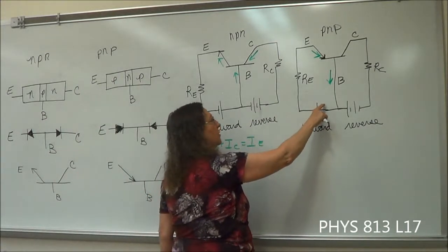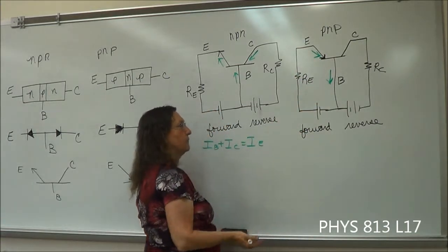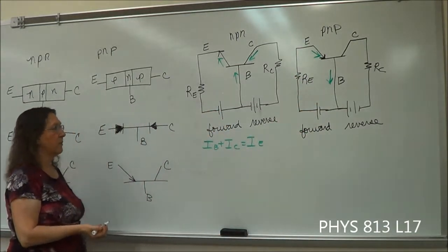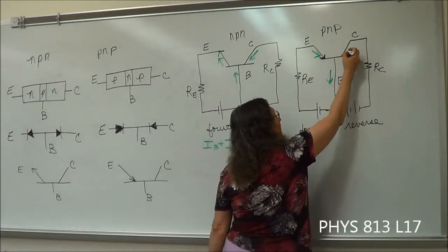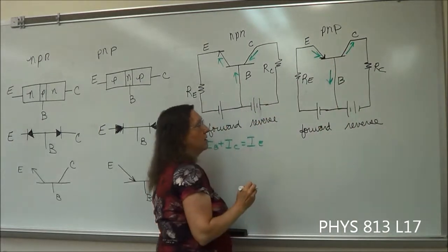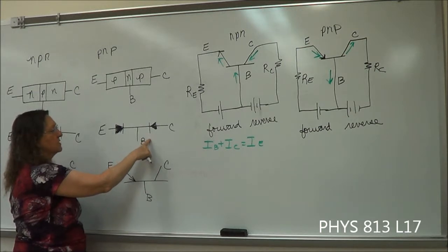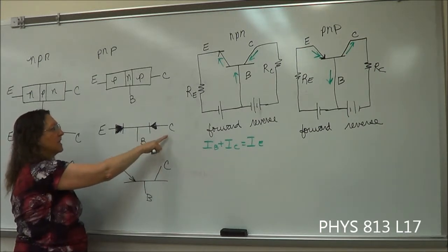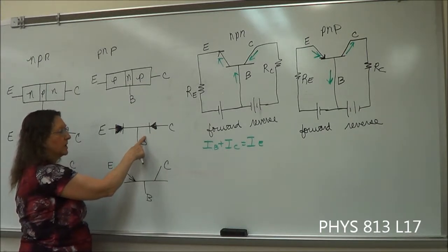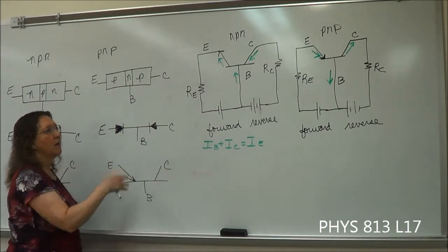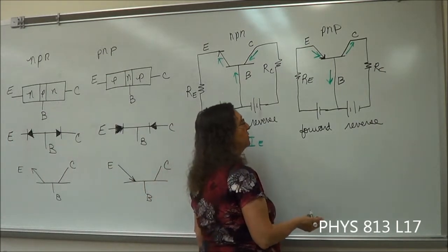So this one with forward bias, we have current going in a loop in a normal sense of operation. Now, for our collector, we're going to have current leaving the collector. And if you look at our diode representation, current leaving the collector is going against what we would normally expect for the diode. So that's why we have a reverse bias there so that it will actually do that.